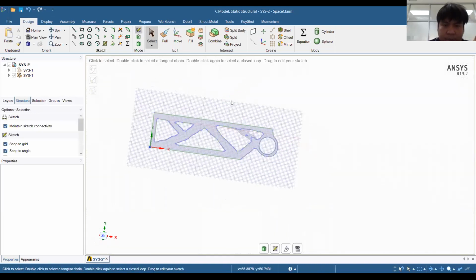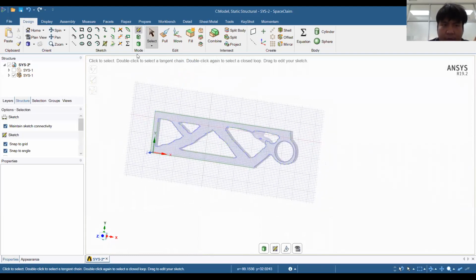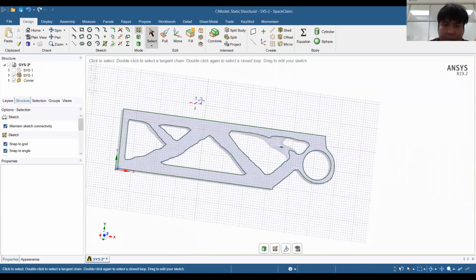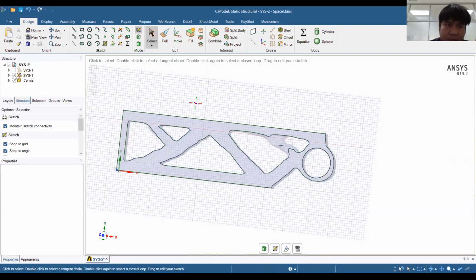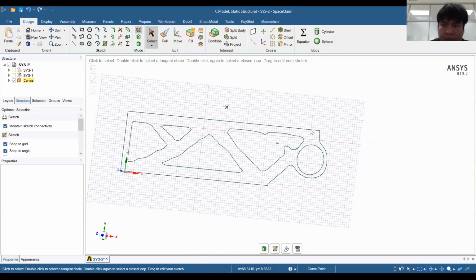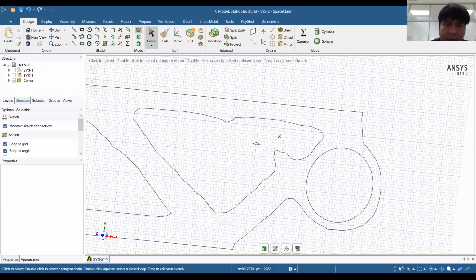Okay. After that, I drag with the left mouse click here, select all of the lines, copy here and paste it. Okay. For now, I got the projection line. Okay, and I turn the optimized part off, and I reconstruct it manually.